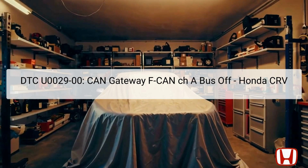DTC U0029 indicates a CAN gateway F-CAN path A bus off error in the 2017 to 2022 Honda CRV. This error occurs when the controller area network, CAN, gateway cannot communicate over the F-CAN channel, which is responsible for relaying critical data among multiple control modules, such as the Powertrain Control Module, PCM, Transmission Control Module, TCM, Vehicle Stability Assist, VSA, Modulator, and others.